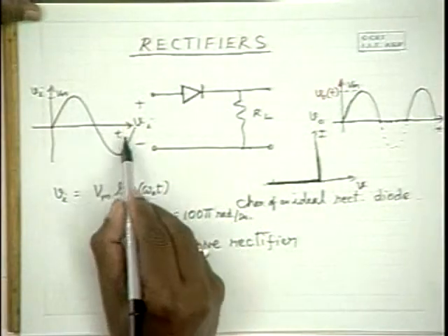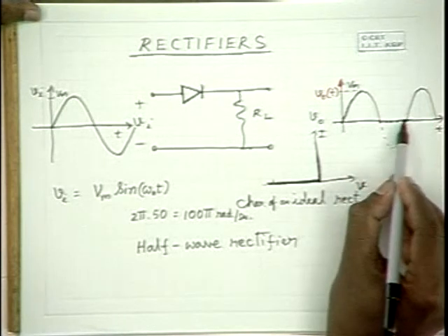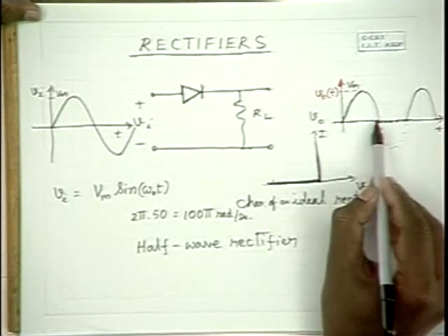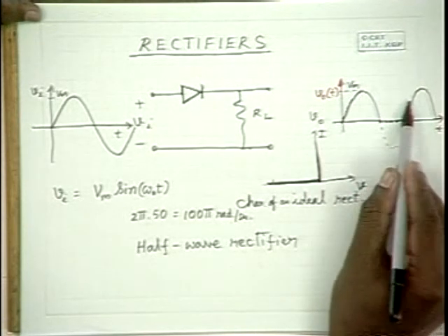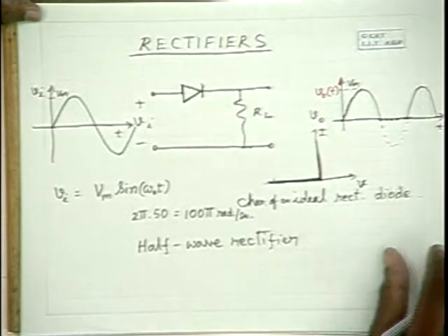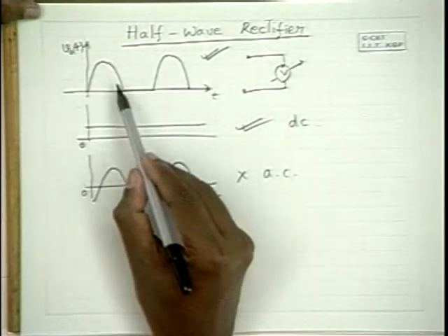Let us continue our discussion on the half-wave rectifier. So in a half-wave rectifier, for an applied voltage of this kind of sinusoidal signal, you get only the positive peaks remaining, positive half cycles remaining, and the negative half cycles are flipped, and you get a zero waveform here. And as I explained earlier, the half-wave rectified waveform